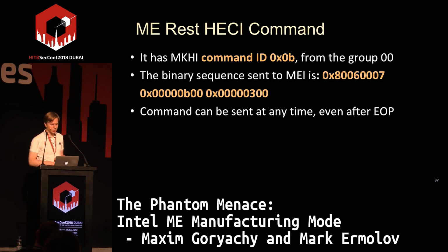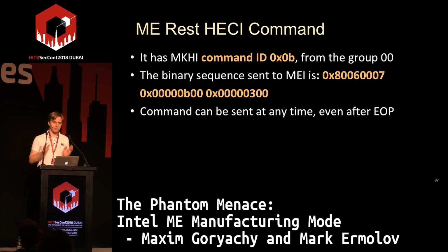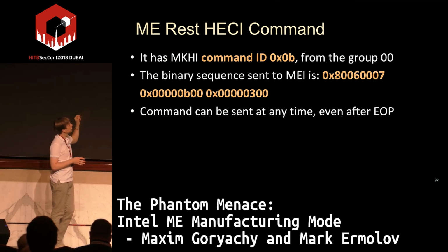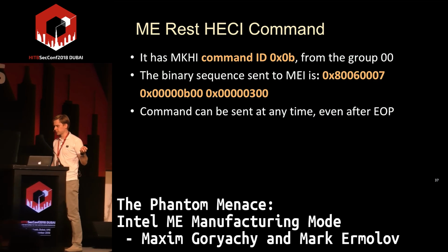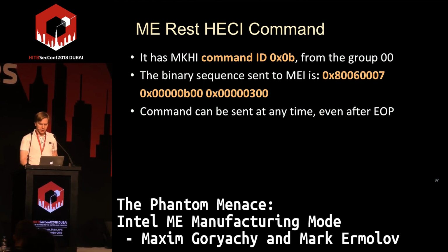Okay, so when we explored the internal ME modules, we discovered another HECI command for a reset of only ME. You can find the full description of this command there. If I remember correctly, 3 means ME reset, 1 means global reset, and 2 means soft reset. Additionally, this command can be sent at any time, even after the end of POST.